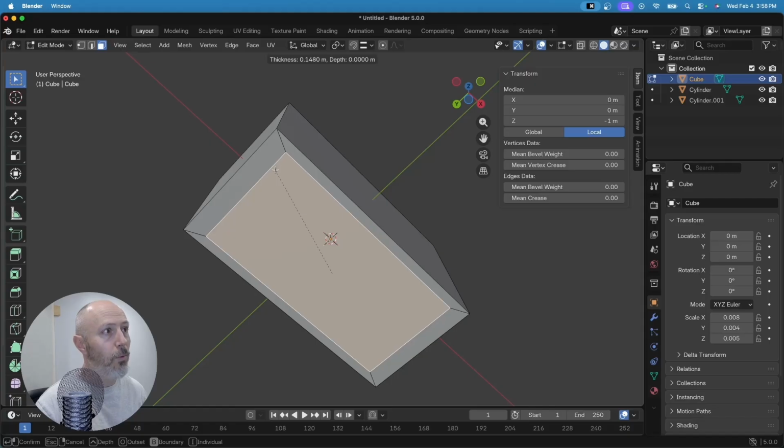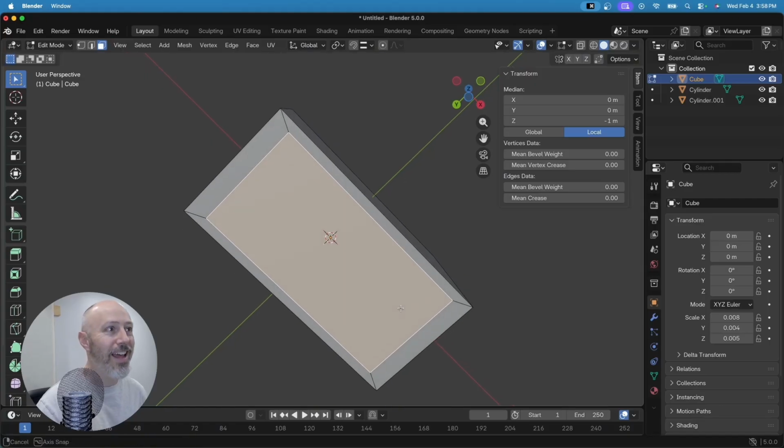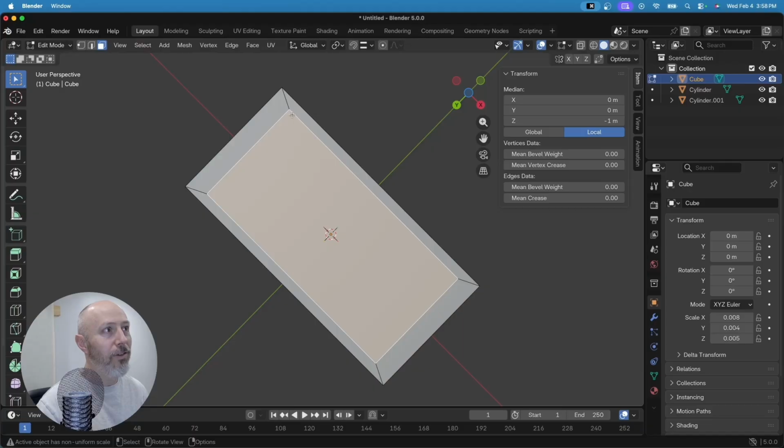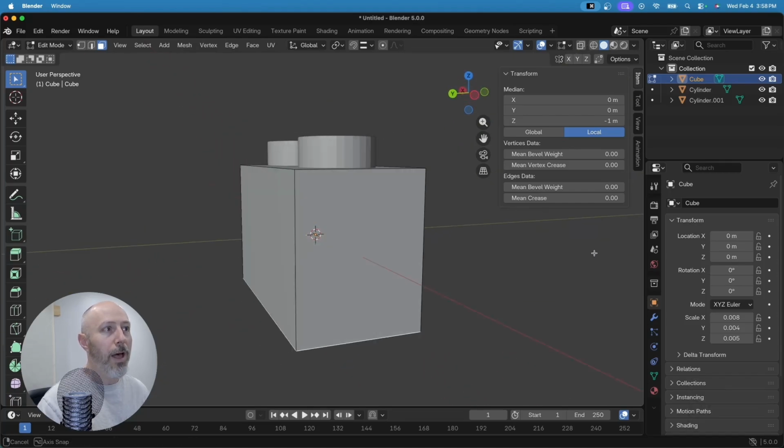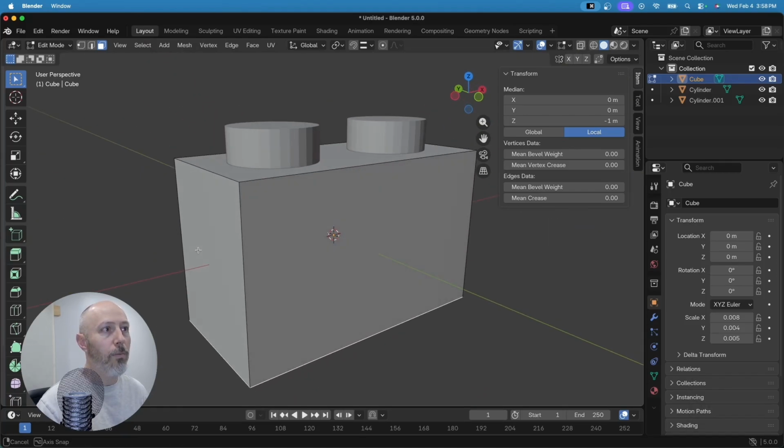And inset is wonky. And I know why that happened. Notice the shapes that have been created are not even all the way around. Notice these ones are really wide and these ones are less wide. We're going to undo that. And the reason for that is I have not yet applied the scale that I made. So I took my 2 meter by 2 meter by 2 meter cube and I resized it in all 3 dimensions, and I resized it different amounts in all 3 dimensions. So what that means is that my scale is actually all messed up now.